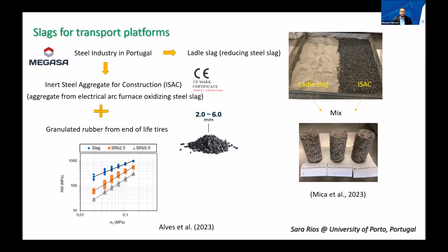That's really good, because if we directly use cement, then cracking is a problem. Of course, cemented materials are always brittle, so they can have some cracking due to a large number of cycles. That's why when we test these materials, we try to use cyclic triaxial tests up to 1 million cycles to evaluate what happens.